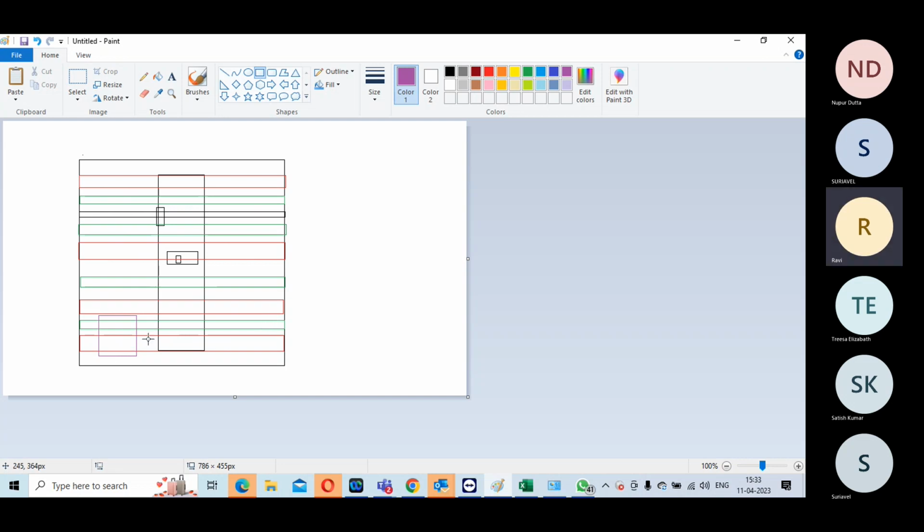Only the switch decides whether it has to be turned on or off. All this circuit flow will get connected to green only. All the mesh will be between green and this particular M1 metal. It won't be between M12. M12 to this green should not have any connection. If it is there, it will be a short.